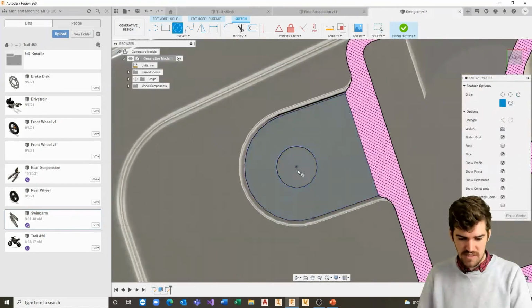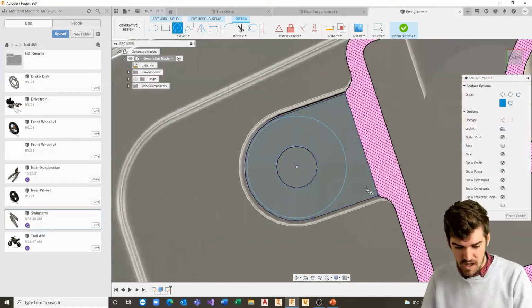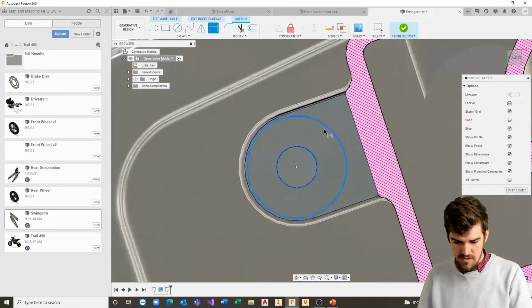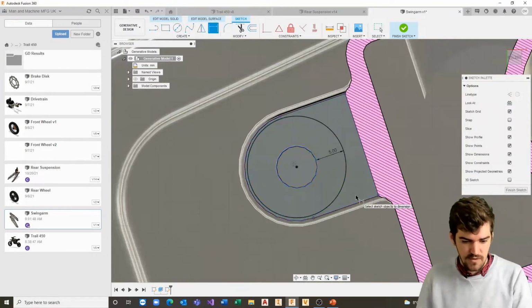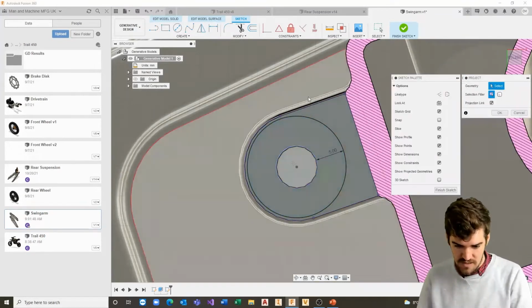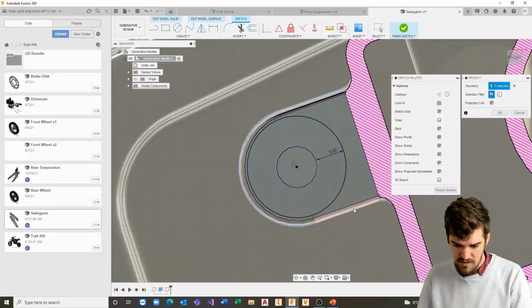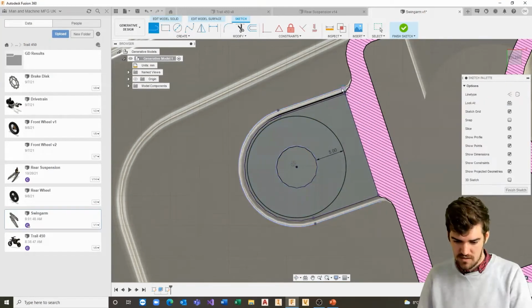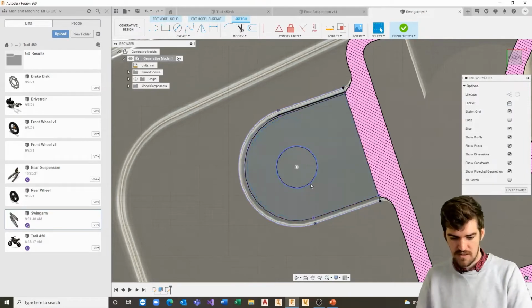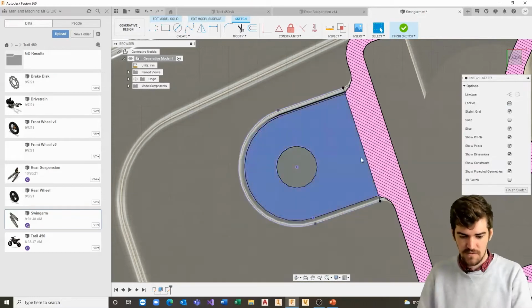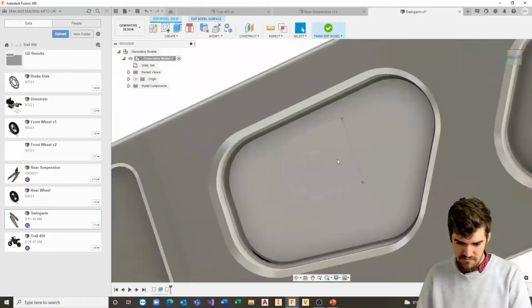This particular point probably not going to make as wide as the last one, so we're just going to set this one to about 5 mil. In fact, what I might even do as part of this one is just project the existing one and almost get an exact replication of the original shape here. So just going to add a quick line down here and maybe remove some of the geometry from there. So you can see this is a direct representative of the original shape. So if I just finish sketch on here, just make sure that the profile is complete. Yes, it is. Cool.